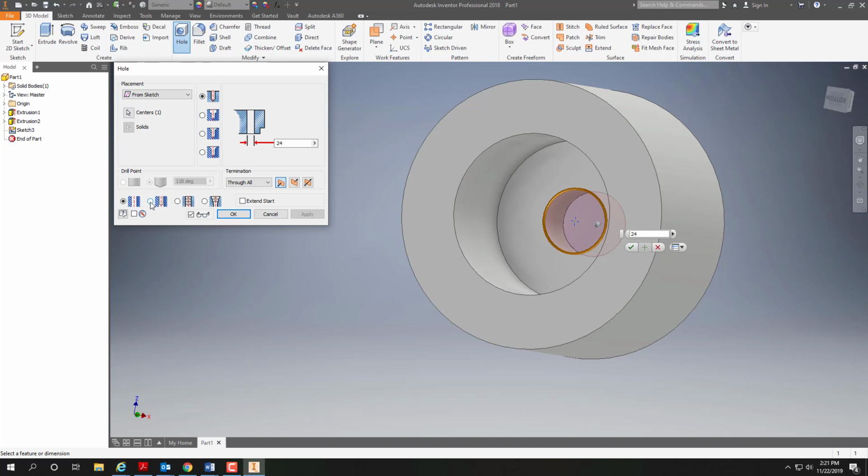Now, the clearance hole, if you have a hole like we're going to have on a plate up here, and you want that to clear, it has to be larger than the nominal diameter, okay? And for a 1/4-20, which is 0.250, you would use an H, I believe, or an F drill bit, which is 0.257. It gives it 7/1000ths of an inch clearance so that you can get that bolt through there with no problem, okay? But we're not doing that on this part, but we will be on the next one.